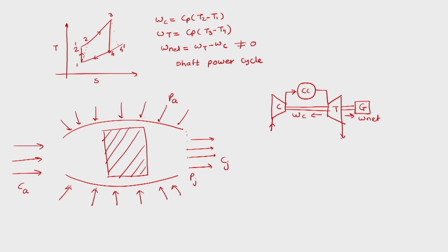So, the point is here we are getting the velocity which is almost the velocity coming at the inlet to the compressor, since the cycle we have drawn here is drawn for the constant mass case. So, everywhere we have the same mass. Obviously, we will add fuel, and then the mass of fuel is neglected. Otherwise, here we have mass of air, here mass of air plus mass of fuel, and here again mass of air plus mass of fuel, and in case of an open cycle we do not have anything, but we will again take air, which is mass of air at 1. But if we have a closed cycle plant, then we will not have mass of fuel, and it becomes mass of air everywhere.